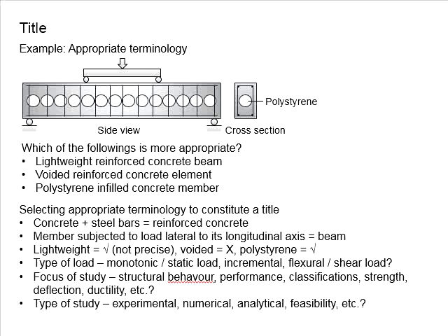And then you might want to know what kind of load you are simulating in this experimental setup. Are you simulating the flexural conditions, or are you actually looking for the shear failure? Whether it is considered a flexural or shear load is very much dependent on the two point loads acting on the member caused by the static load.